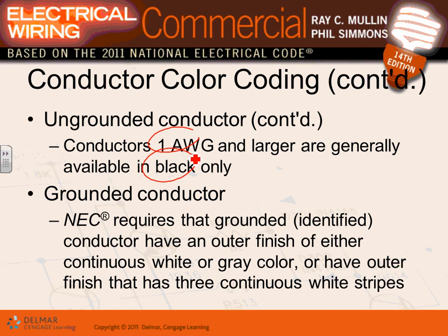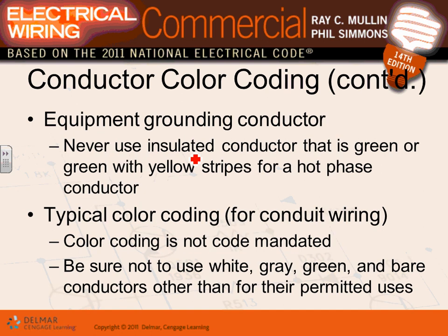Any comments, guys? Any questions about identifying the color code for your conductors? So important in a commercial building to do that. You guys are not electricians, but to be a project manager, I always say, guys, to be a project manager, designer, the more installation you know, the better designer you will be. No question asked. So, telling you, the equipment grounded conductor shall never be used as an ungrounded conductor. The ground never used as a hot. That's basically it.